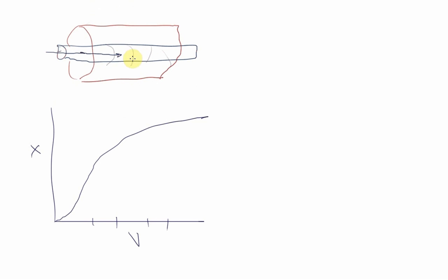Right, so what we really want to do is accumulate the heat added to the fluid as it's passing through the tube, right? So in this case, we can say we would rather evaluate the temperature variance across the tube, and if so, we should actually also monitor the temperature variance in the tube itself. Well, there we could actually say if the flow rate through the heating or cooling tube, if the flow rate of the heat exchange material is high enough, then the temperature on the tube side could be approximately constant, right?